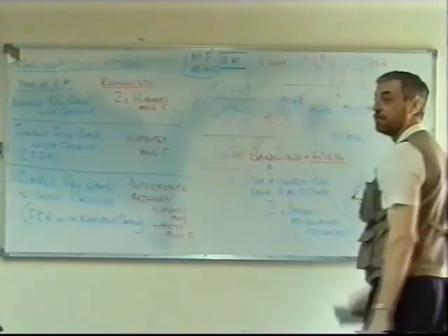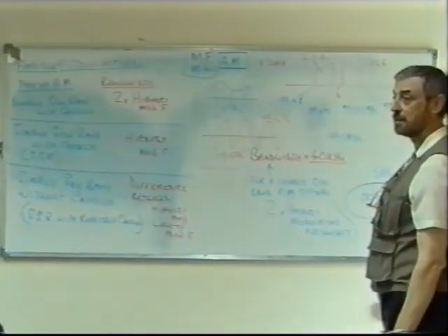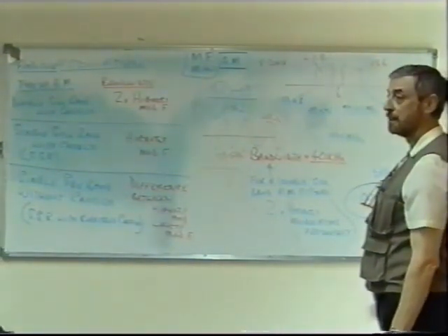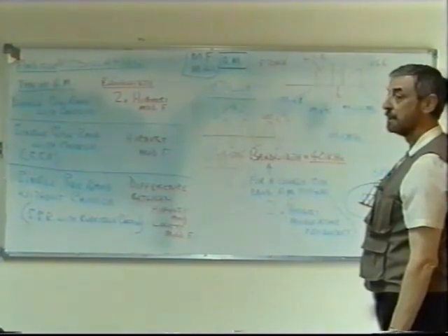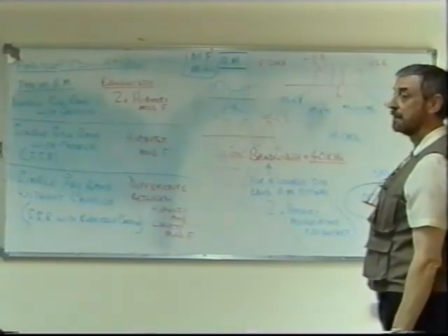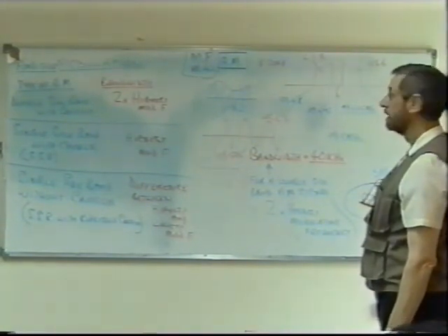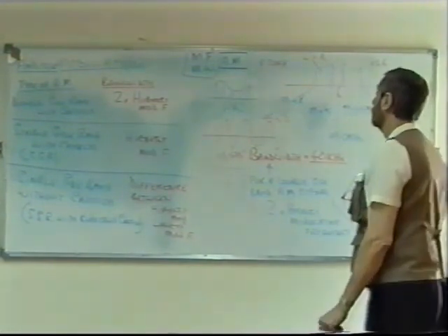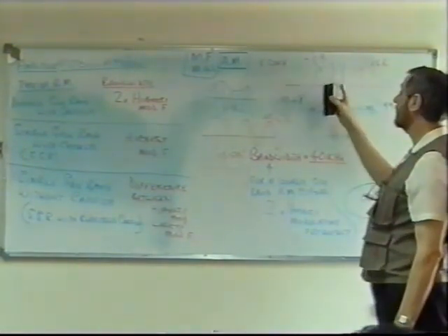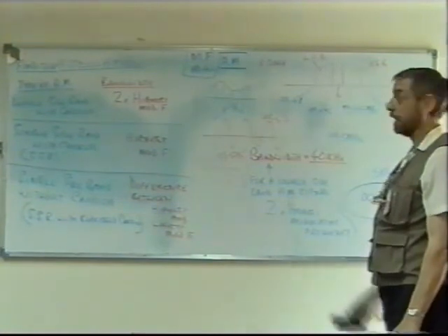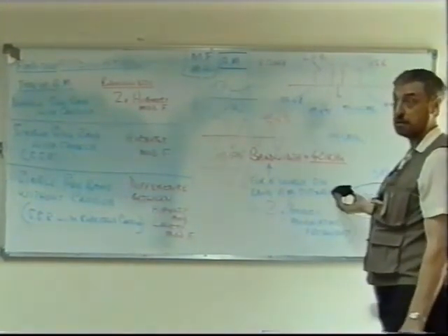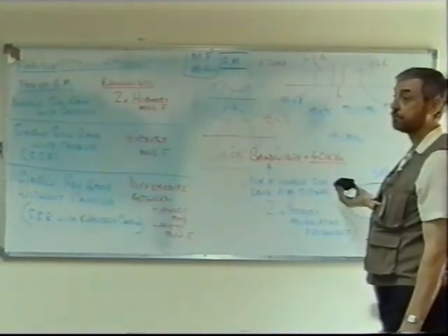You don't use the DC for the carrier. You don't use this side for the carrier. You only use the lower sideband, the high sideband. Then the bandwidth will be 30, not 40. No, the position of the sidebands, there's a gap in between of 10, in this example I showed here. You can't change that.